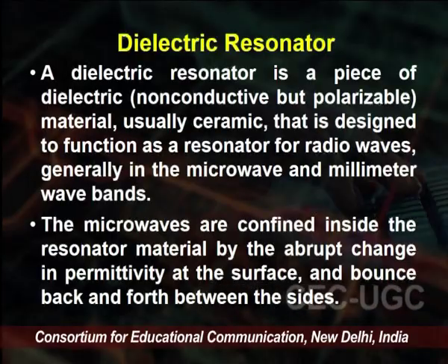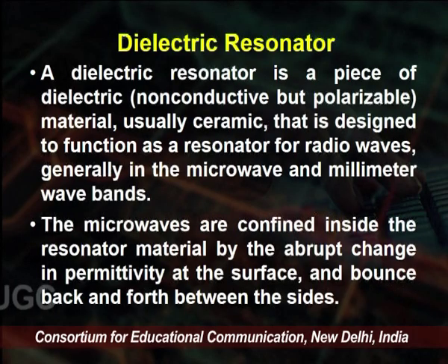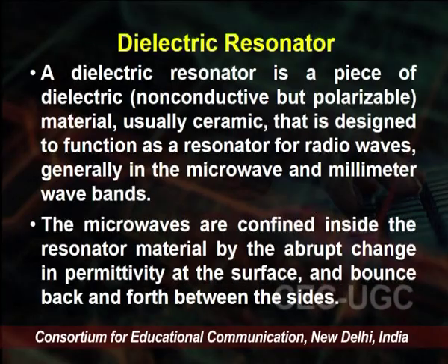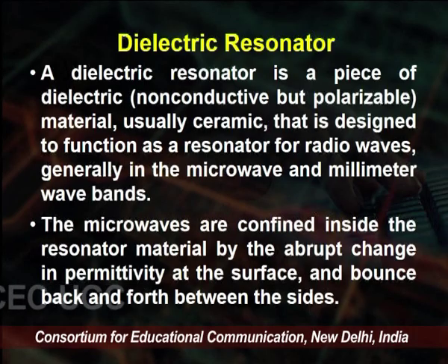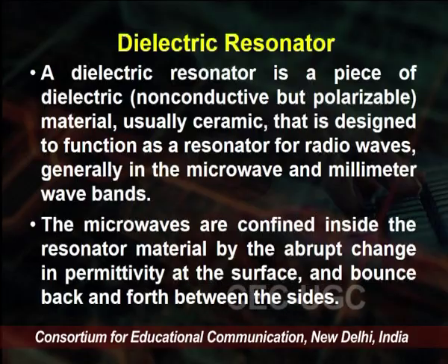So, these are the types of MEMS resonator. Now, we discuss the dielectric resonator. A dielectric resonator is a piece of dielectric, or we can say a non-conductive but polarizable material. Basically, we use ceramic that is designed to function as a resonator for radio waves, generally in the microwave and millimeter wave bands.